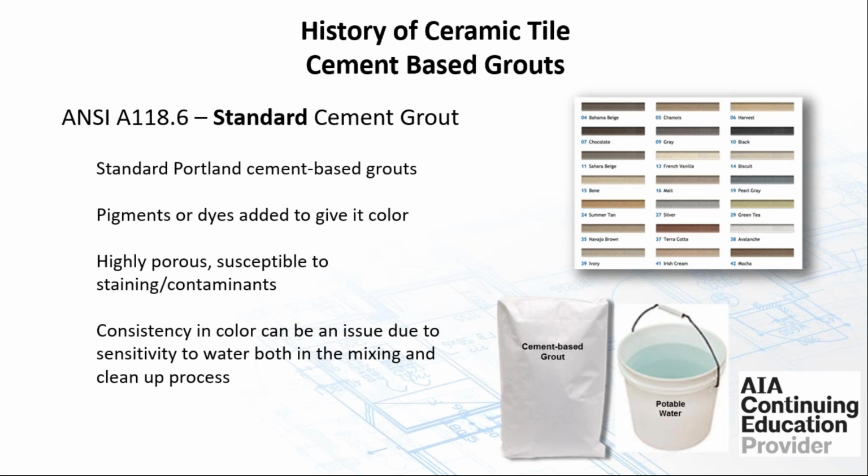Consistency in the color can be an issue due to sensitivity to the water being used in mixing and the cleanup process. From your basic knowledge of cement, we know that cement doesn't need that much water to hydrate and to turn it hard. But what we have to have is a water of convenience to make the product flow, getting it out and into the places that we want.